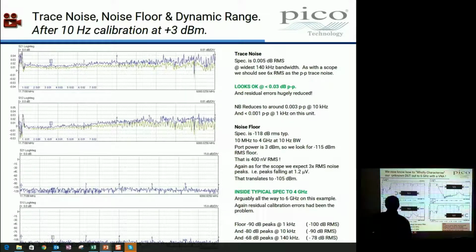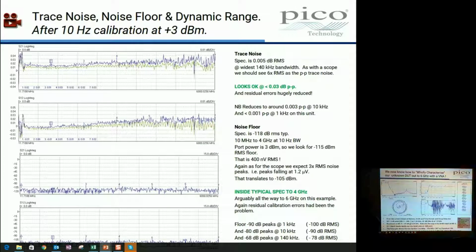Did anything move? Yeah, so I think you conclude it's a well-behaved steep and deep low-pass filter. To a degree, it's re-entrant around 4.2 gigs. Match is not brilliant, but it's okay, out to a gigahertz. As a general guide, match minus 20 dB is pretty good for most microwave applications. It always depends on what you're doing, and maybe sometimes you need minus 30. You're probably never going to see minus 40. It really doesn't get that good very often. And as we said, the device is reciprocal.